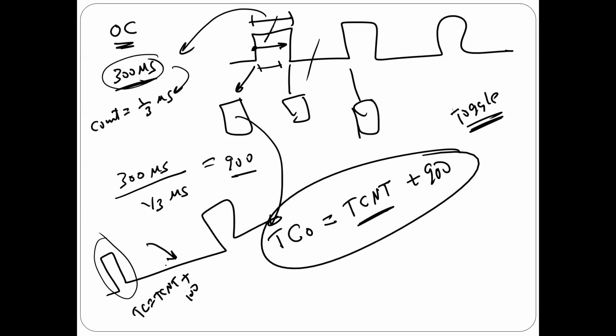However, this time, I'm gonna say TC equal TC in T plus 900, for example. You got what I'm saying? It doesn't need to be the same, but I need to know, because it's just one interrupt subroutine, I have to know if this is high or low. So if this is the signal for high, I'm gonna use this statement, else use this statement.